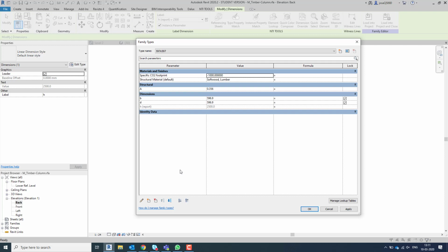At this point, I need to create a parameter, a shared parameter, because everybody knows where shared parameters are, right? It's a text file. It's a text file that's going to be applied into the family, into the project, and into the tag.